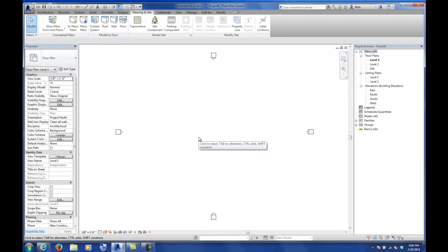The reason why Revit always hides those is it assumes that you were using that as some kind of underlay for your base geometry, to apply like a wall or a floor, and it just by default always wants to turn them off. That's going to be important because when you start to do renderings or try to represent this on a piece of paper, you'll load up your project and you'll see that all your masses have disappeared, and it's just because they've been turned off. Every time you load up Revit, it tends to turn them off by default.